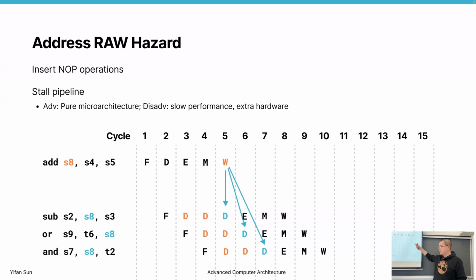It tries to make the pipeline, the control stage, super simple, so that we can have a lot of die size, a major die size, dedicated to compute. Okay, so that's the philosophy difference between a CPU design and a GPU design. CPU has complex control, but GPU has simple control, but more die size on the ALU unit that can provide more compute power.